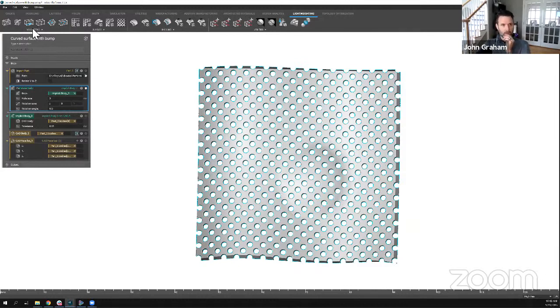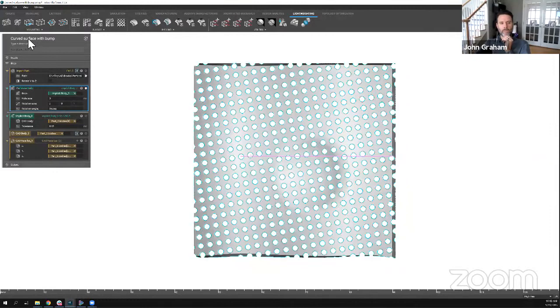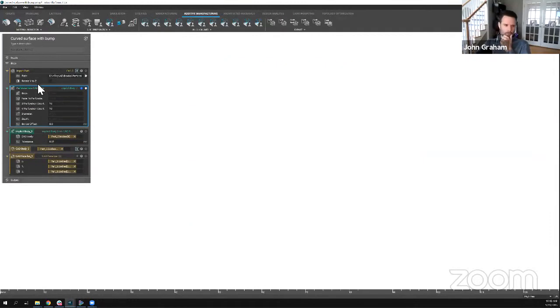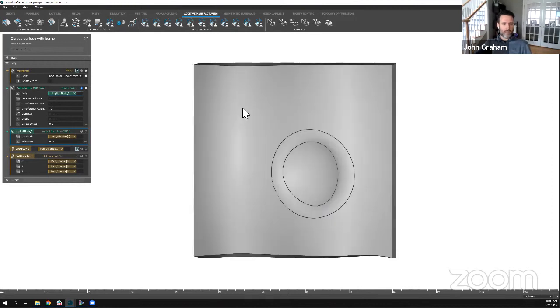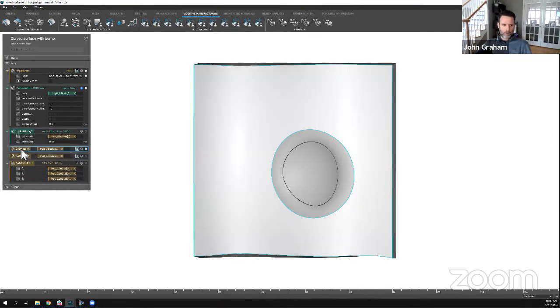Now, speaking of applications, one of the things that we know our customers like to do is when they're doing a 3D printing process that involves powder, and you're shelling out a body and maybe putting a lattice on the inside, you can't just do that without making some kind of a series of holes or a hole from which to extract out all the powder, right?